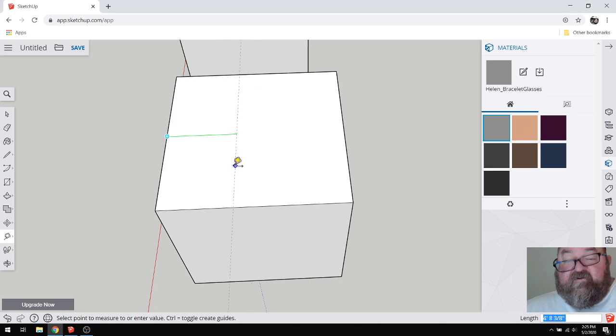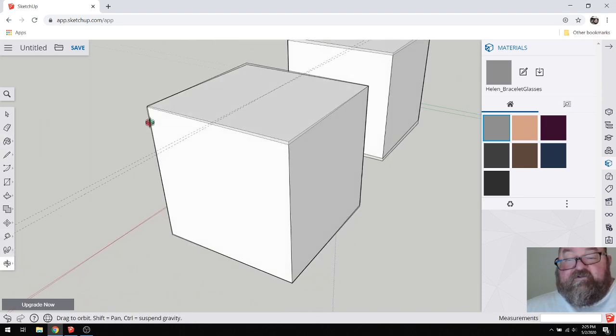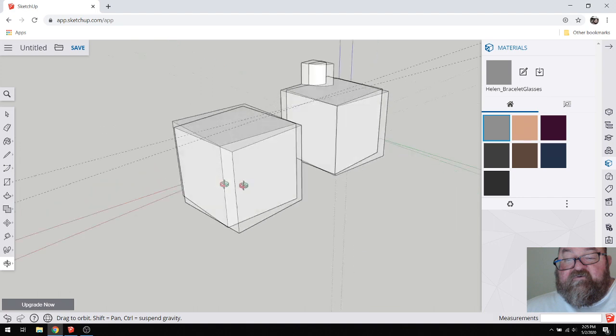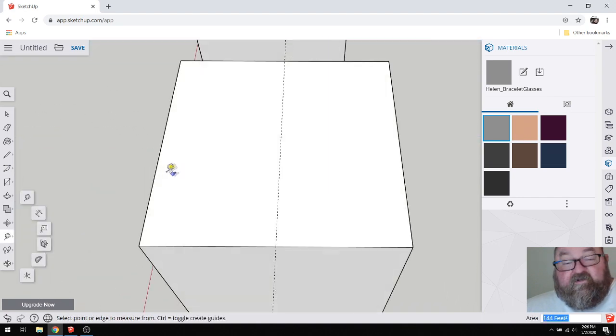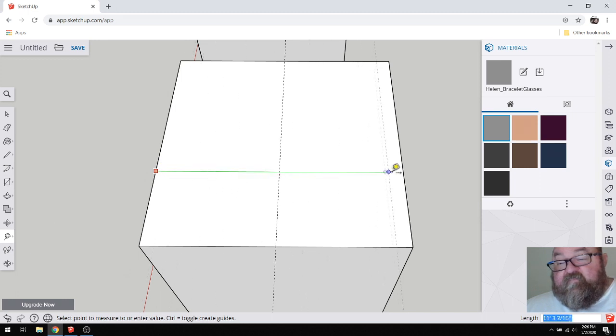You'll see it's creating this little dashed line, right? I can reference the center, which is 6 feet, and now I've got a construction line. That construction line is sort of a concept in CAD. It just goes for infinity. You can also just measure things. Like if I pulled it all the way across here, you can see it says 12 feet.